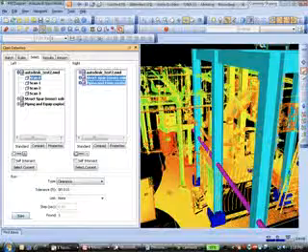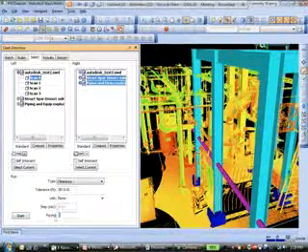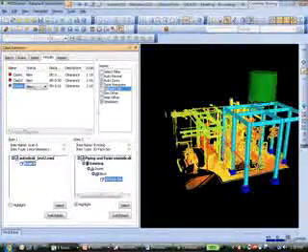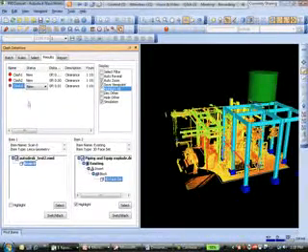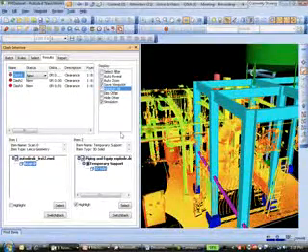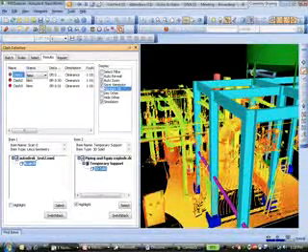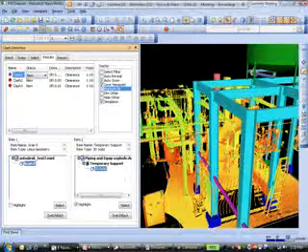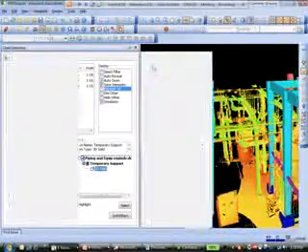And in doing so, in this case, you can see it found three clashes. If I go over to the Results tab in Navisworks, now it's going to show me not only these particular clashes, it's going to highlight them on screen, but it's going to now take me into that particular view. Now, because we have a lot of different colors on screen, what I will typically do is I will go ahead and